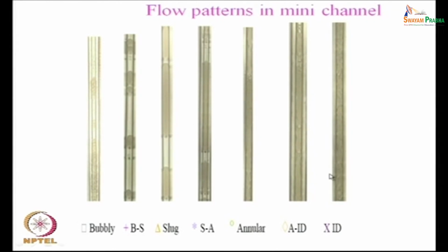So, we find that under normal circumstances in liquid flows, we do not have this slugging tendency, but as we go to smaller pipe diameters, the differences between air water and liquid flows gradually reduce and we come across more similar flow patterns in the two cases. Okay. So, this shows the effect of fluid physical properties, or the fluid type, on the flow distributions.